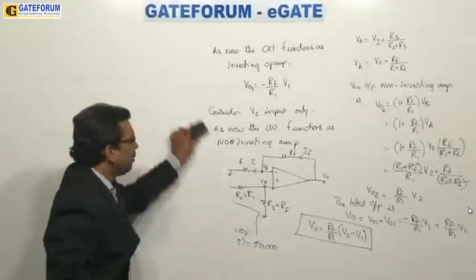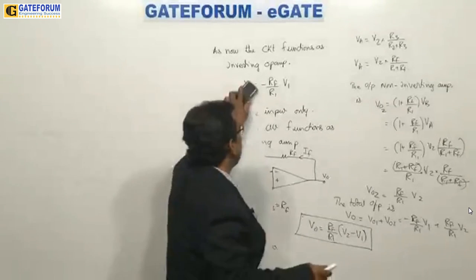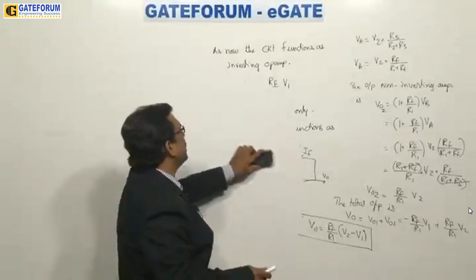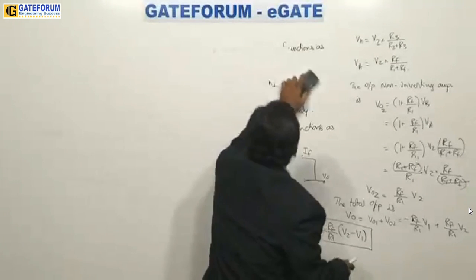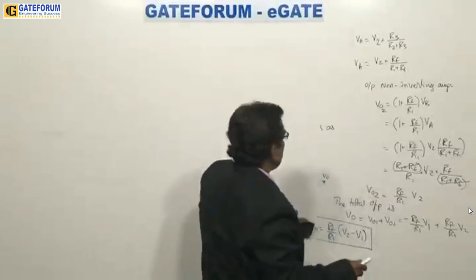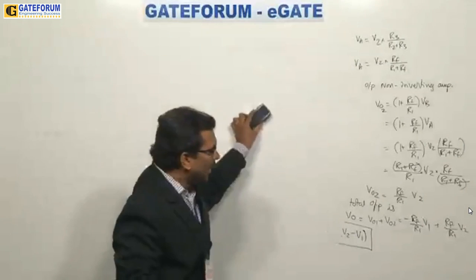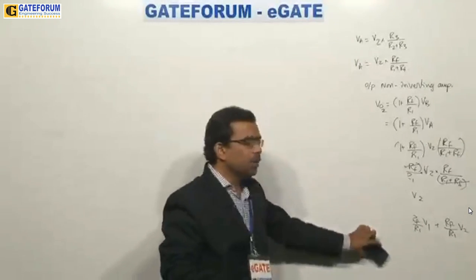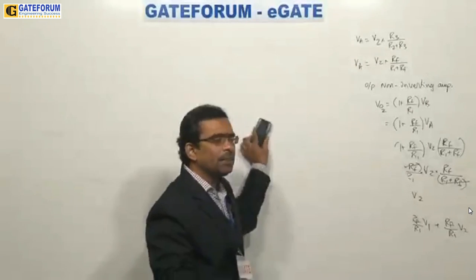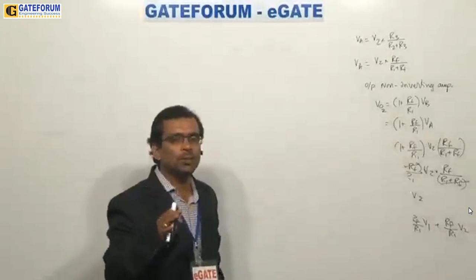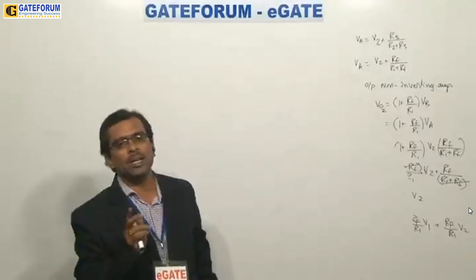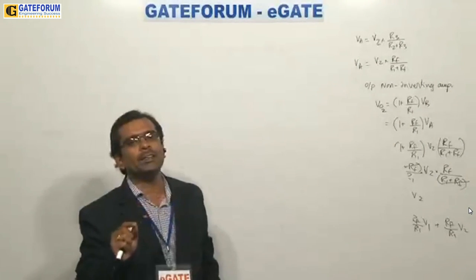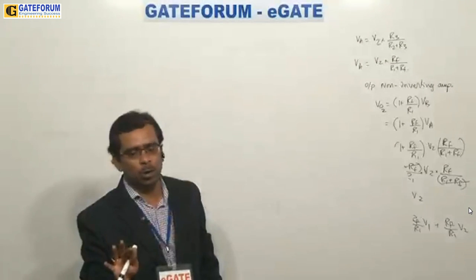So now that you have seen the amplifiers, and just now why we study the DC characteristics here is, earlier DC characteristics studied in transistor is for biasing. But here the biasing job is done by the manufacturer itself. He provides all the internal connections and biasing is perfect. Only if you provide VCC, automatically the transistors are biased and you will get faithful results.